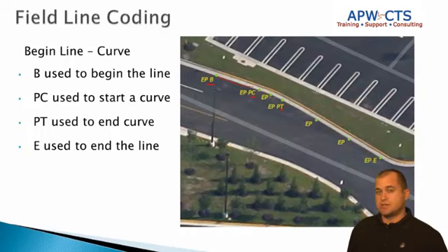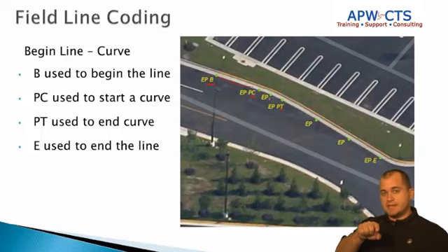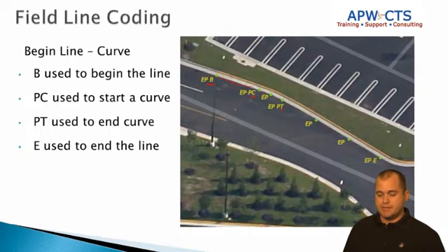Now, you also notice that I took a shot in the middle and I just called it EP. The software will pick that up and make it part of the curve as it draws this line. You could also get away with just using three points and not using that PT. If I do the PC by itself, then an EP for the second shot and an EP for the third shot, which is the PT, and don't put PT, it'll still draw a curve through there, because when it sees PC by itself, it assumes a three-point curve.